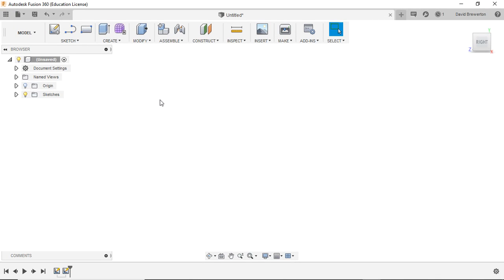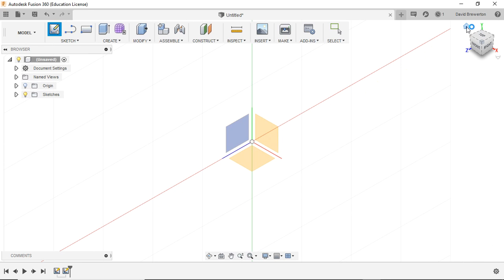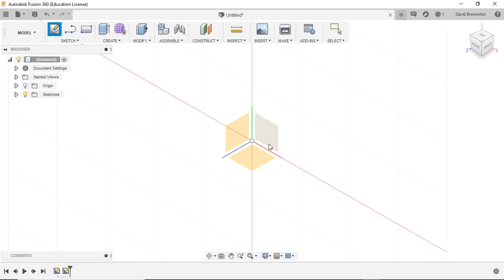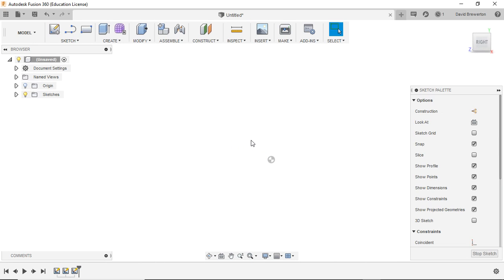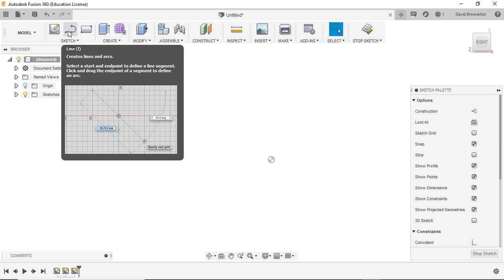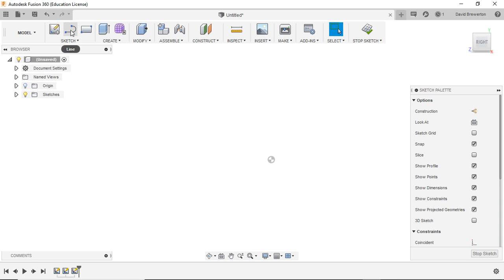Okay, in this video, we're just going to go through creating the sketch for the Lego head drawing. So the first thing we're going to do is click on sketch, create sketch, and then we'll go back home, click on sketch, and select which plane we're going to do it on. So we're going to click on this one here. It doesn't really matter which one it is, either way it still works. And then from there, we're going to create a sketch.